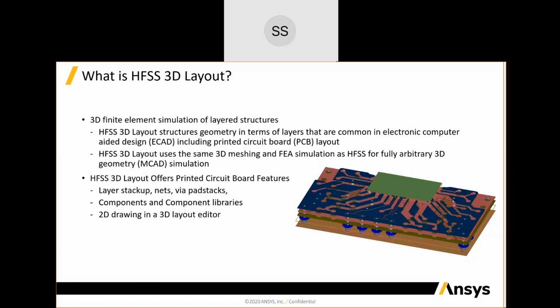And then when we're solving it with the HFSS solver, we're not taking any shortcuts. We're not assuming that dielectrics are infinite in size or the metal layers have zero thickness. So we're analyzing everything the way that it's defined within the geometry.